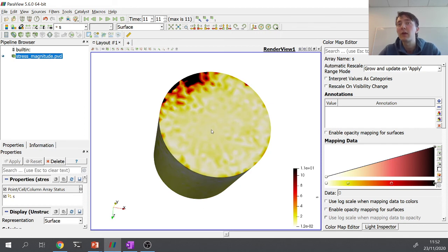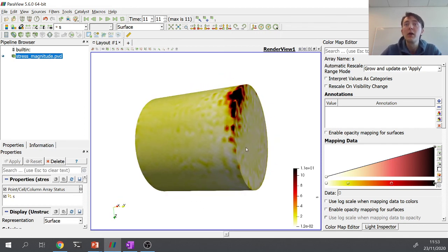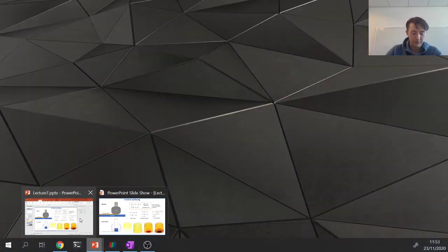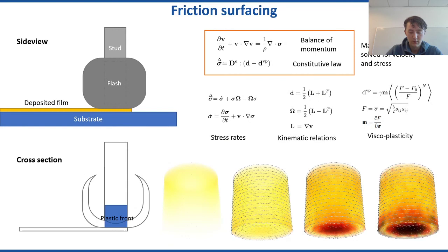So then again, we have to think about where these instabilities come from. We're dealing with a nonlinear problem. We're dealing with a problem that has this advective term. But I'm also dealing with a problem that is of a mixed nature. The mixed nature means that we have two different solution fields that we're solving for at the same time, sigma and v.